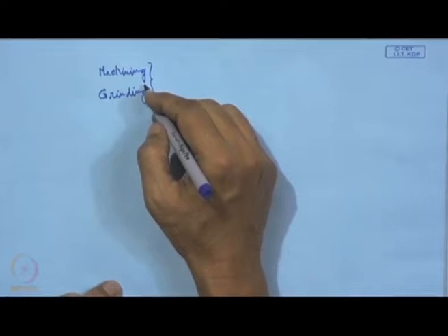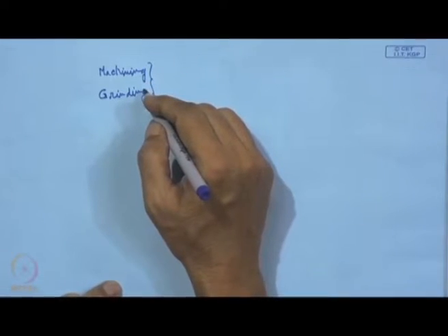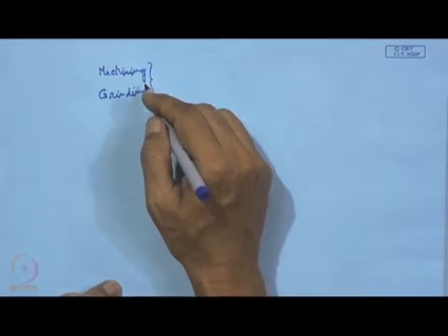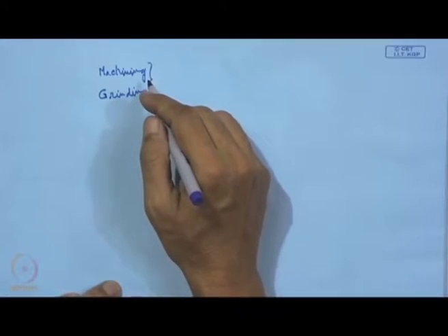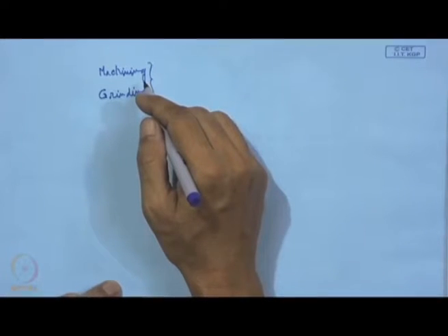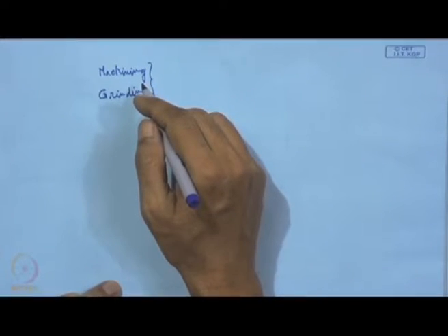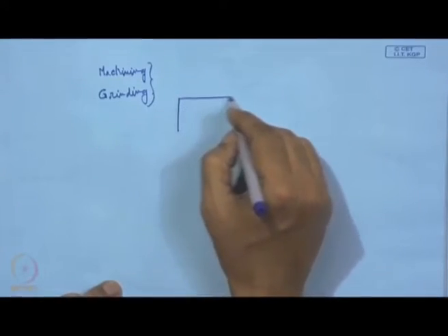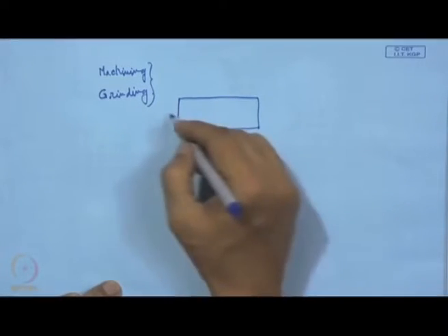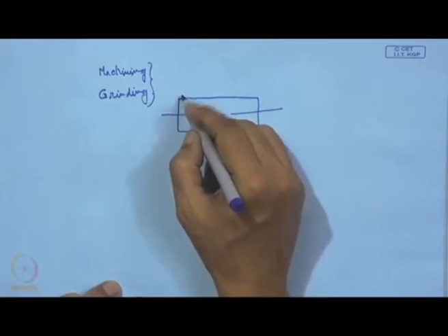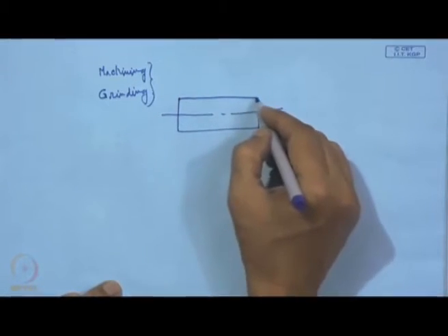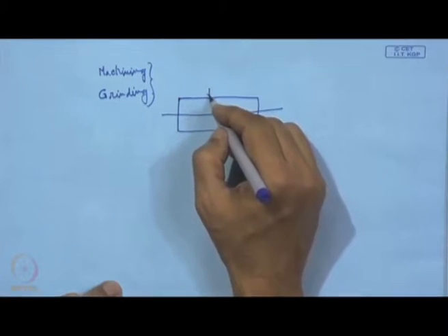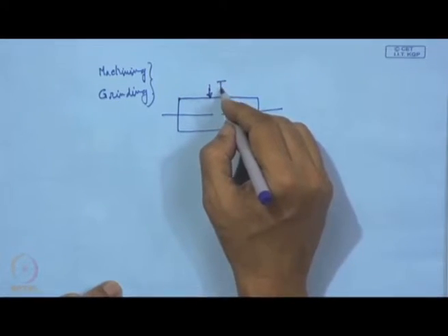This is number 1, and number 2 is that there can also be high residual stress because of the unequal cooling between the top surface and the core area, that means a high temperature gradient. As a result, on the surface, whether it is cylindrical or flat, this is actually the functional surface, and on this surface the residual stress is tensile stress.